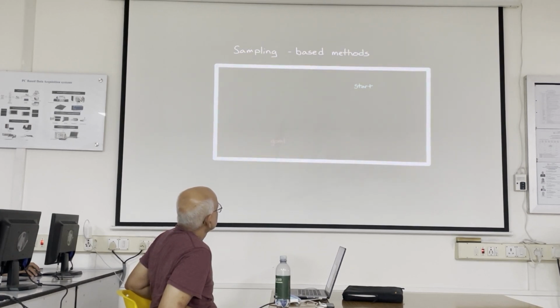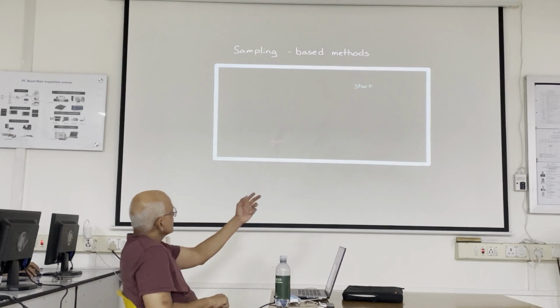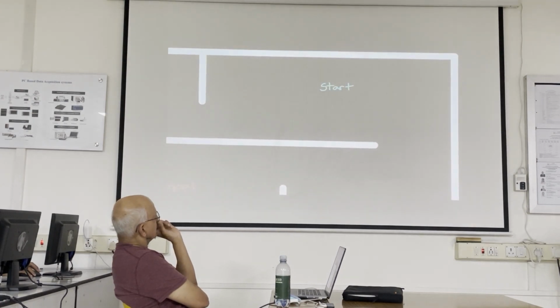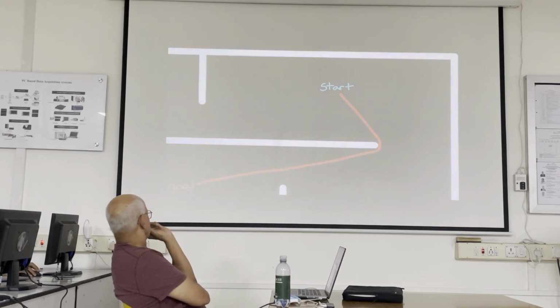To understand how sampling-based algorithms work, I think it's first helpful to realize that in our map, and probably most maps, there are sections where a path could continue in a straight direction for some distance before it needs to make a turn. With A*, we have to calculate every single grid cell between these 2 points, so multiple nodes in the tree. However, if we only checked the far distant node and there weren't any obstacles in the way, then we could calculate the straight line cost for just this one node.